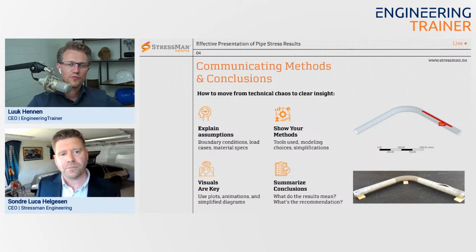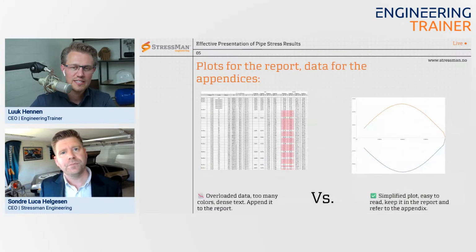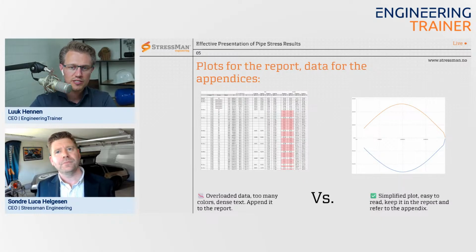Hey, we've got one comment from Pankaj. Pankaj, thanks for sharing. He mentioned the ASME B31.3 Appendix S also covers reporting, like what exactly to report. So obviously there's like the list there. Yeah. Pankaj, you also mentioned, first of all, thanks for sharing your thoughts and experience. You also mentioned, Pankaj, in the UK, our reports are reviewed by the client and third parties like DNV and Lloyd's. It is needed for the PED, the Pressure Equipment Directive, DOC, the Declaration of Conformity, which is the European legislation.